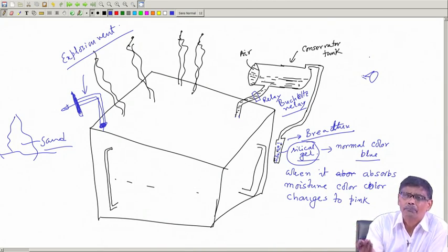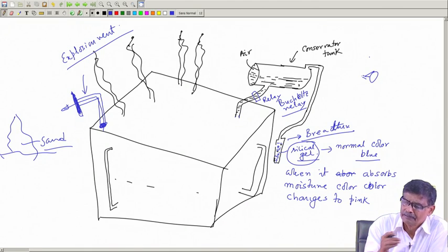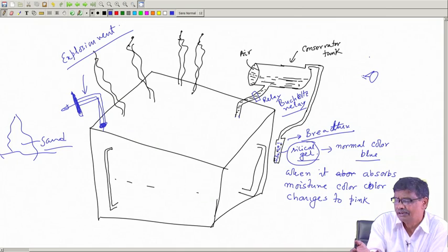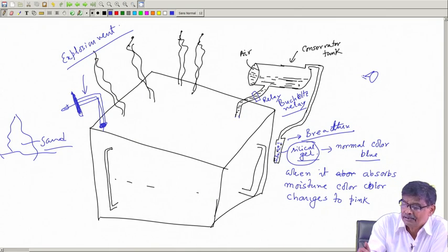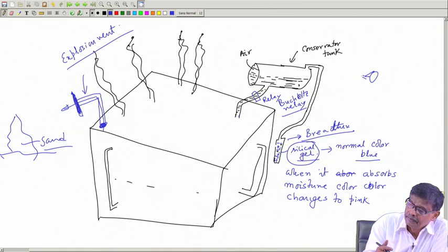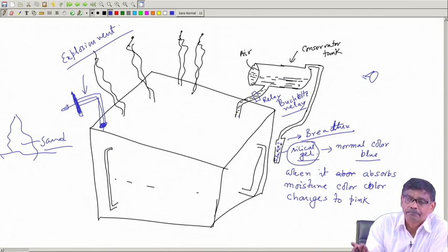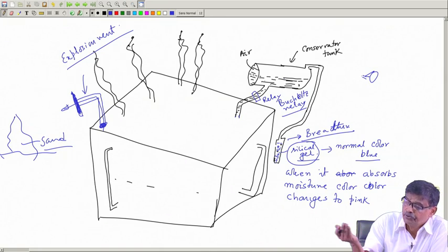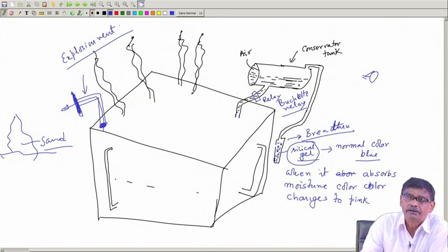So, it will go up because density has fallen and that movement is used. So, we are not discussing that, but I will just mention there is a place in these connecting tubes where a Buchholz relay is connected and it will operate and give you an alarm, or if necessary it will disconnect the transformer. You will read those things in power system protection.